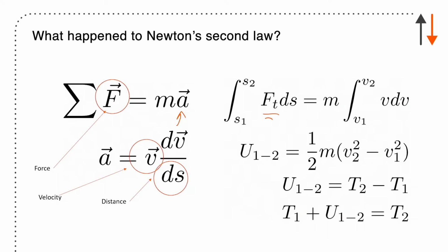So I'm just splitting the derivative and putting the terms out. And so the work from 1 to 2 is over here. That's just that expression right there. And on the other side, I have this new expression, 1/2 m (v2 squared minus v1 squared). And I'm going to call T my kinetic energy. And I've been asked this in the past, why T? T is travail, and it comes out of French. So that's the reason why you have 1/2 m v squared, or T, as your term.